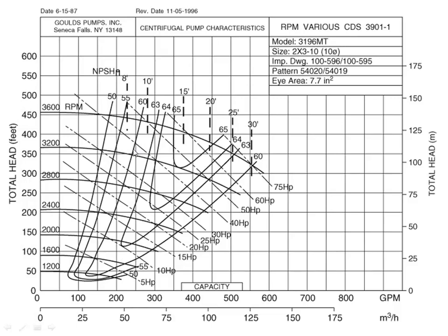These lines refer to the power. You can see 40 horsepower, 50 horsepower, and so they've already sort of graphically solved the power equation for a certain pump head, for a certain flow rate, and they're assuming a unit weight of water in order to calculate those pump powers. And then the final thing here, you see NPSH, and that stands for net positive suction head.